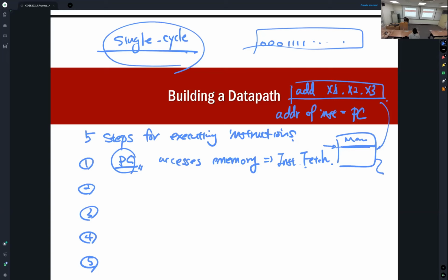So we require decoding, and this step is called instruction decode. We also learned how each field of the instruction data is organized by a certain instruction. So by checking each field of the instruction data, a processor decodes this instruction.